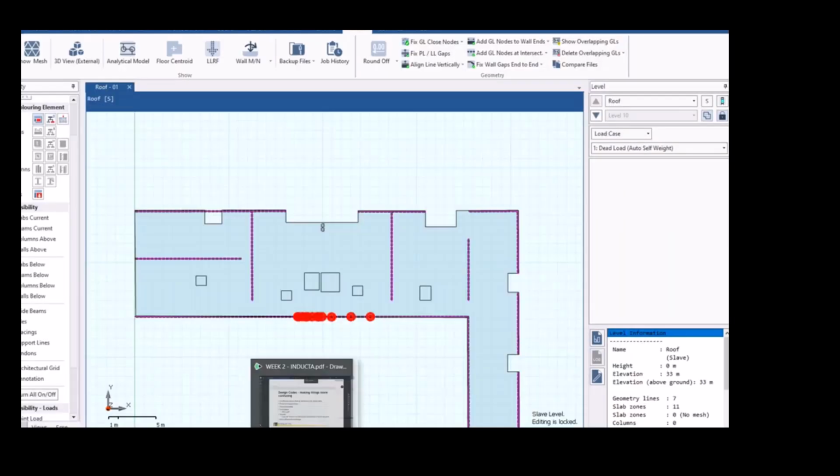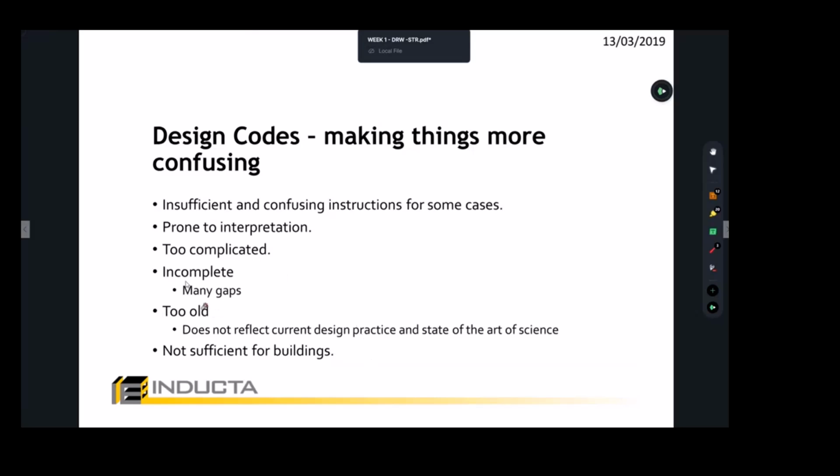So quickly going back to my notes. Yes, how to deal with the standards, as I said, you will experience that as we go through, and you've already experienced that, haven't you? When I ask you to find dead loads or live loads, we have to follow what the standard is telling us to use. That's a very simple example. I already said to you live loads for office buildings are going to be 2 kPa, so that means you already follow the standards. Then standards will be a bit more detailed when we get to earthquake loads, which we're going to do this week or next week.